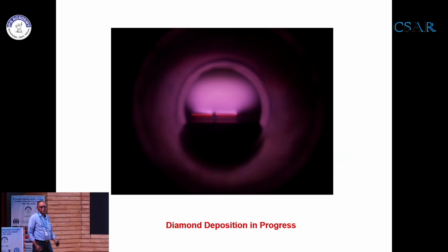And this is how the cavity that you design works. Basically, the plasma region which is showing is the focusing of the electromagnetic energy. By adjusting the substrate holder, which is conducting, and your mode converter, that distance, that cavity which is formed, you focus the electromagnetic energy where you have maximum electric field. And you see this is the plasma generated at 50 to 100 torr pressure. It is a 2-inch tennis ball kind of plasma in which 1.5 to almost 2 kilowatt power is dumped.